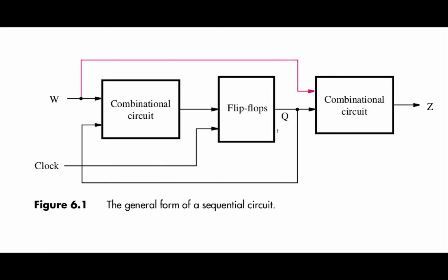The important thing to keep in mind is that the combinational and the sequential circuits are all separate blocks. They're separate entities. They don't share signals. The output from the combinational block goes to your flip-flop, but they're built independently. That's probably the better way to put it. And then finally, when you build a state machine, you put them together in hierarchy and you tie your signals.